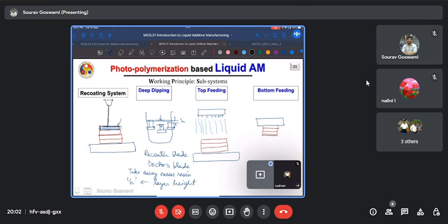The feeding of the fresh resin is actually happening from the bottom. So if this is my vat and I will be moving my build plate along the positive z direction, then I move it by exactly the layer height, to coat the last printed surface with a layer of resin to be utilized for the next step. This may be achieved by several means. It might simply travel up along the z direction, or it might slide in the xy plane to obtain a new layer of resin.